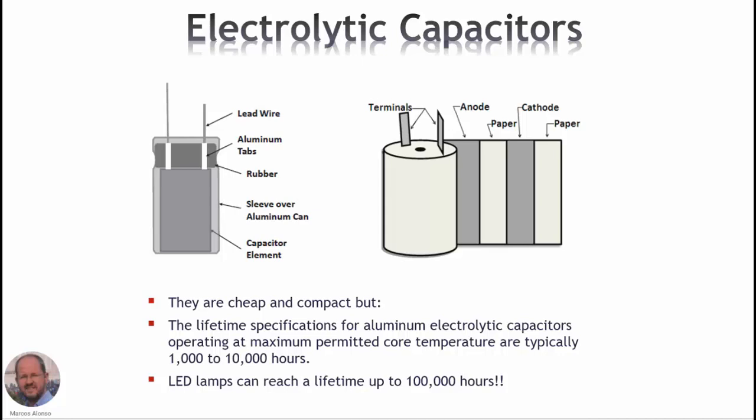But the problem is that the lifetime specifications for electrolytic capacitors operating at a maximum core temperature are usually between 1000 hours and 10,000 hours, while LED lamps can reach a lifetime of up to 100,000 hours, as we know. So we need to avoid the use of electrolytic capacitors in this kind of application because otherwise the driver is going to fail before the lamp itself.